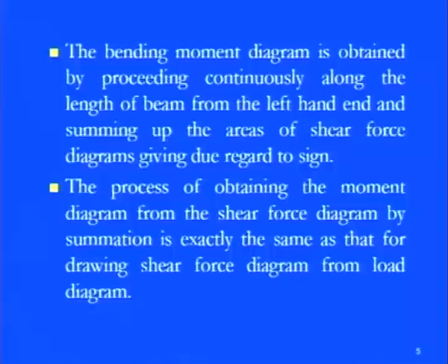So the process of obtaining the moment diagram from the shear force diagram by summing up is exactly the same as that for drawing the shear force diagram from the load diagram, because we discussed that w equals dF by dx. So F is nothing but the integration of w into dx.